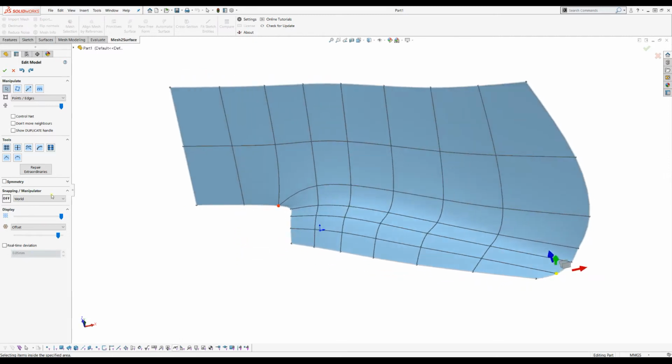The other option is called split edge. The split edge is useful in some cases, for example, when we want to create another split but only in one direction. For this reason, what we need to do is just select an edge. This will mean that it will follow all the quads that are connected in this direction and will just split these edges in half. Let's try this command. I will just select my edge and press split.